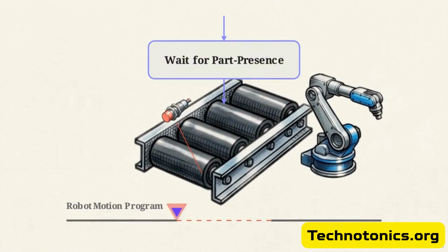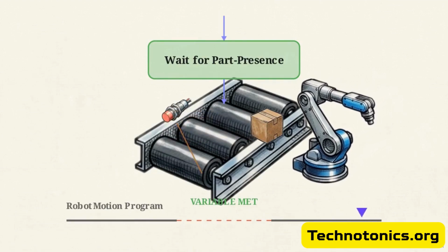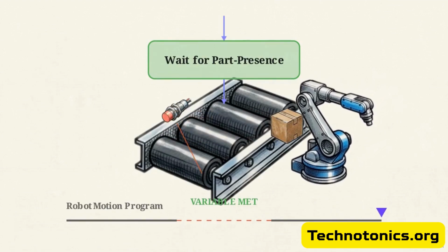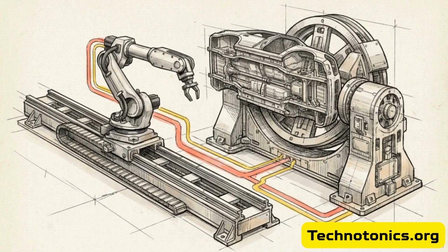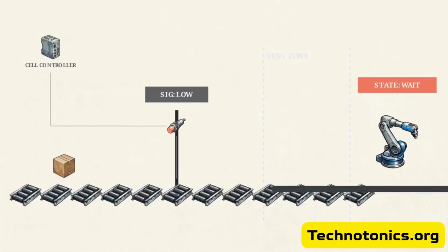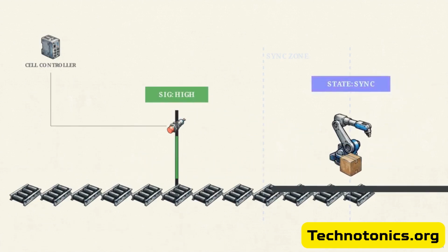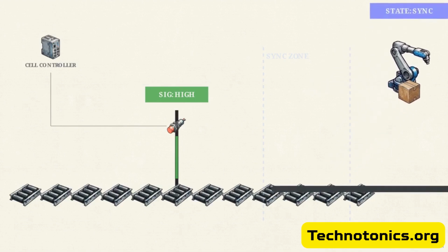We deploy virtual sensors to emulate critical perception logic. When a digital part intersects a beam, it confirms part presence, satisfying the logic needed to trigger the next sequential movement. This logic extends outward, pairing the robot with external devices like rotary part positioners and linear tracks. It also enables the synchronization of the robotic arm with external material handling systems. A conveyor belt introduces a new part, and the arm executes its exact handling sequence in perfect time.